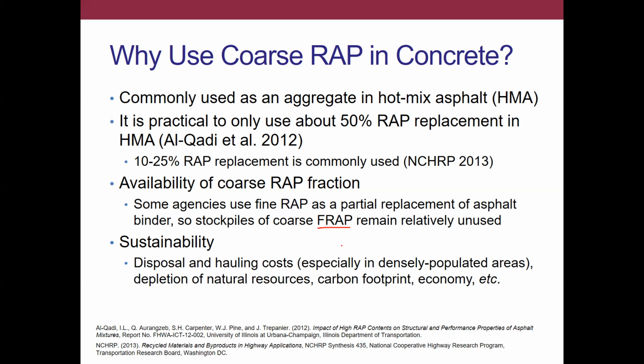So that means that the coarse FRAP, so everything retained on the number 4 or 4.75 millimeter sieve, remains relatively unused. Again, that may not be universal, but it certainly seems some agencies have a significantly higher stockpile of the coarse material. At least for the research that I'll be presenting, or I should say a few studies I'll be presenting on, we were mainly focused on this coarse fraction.